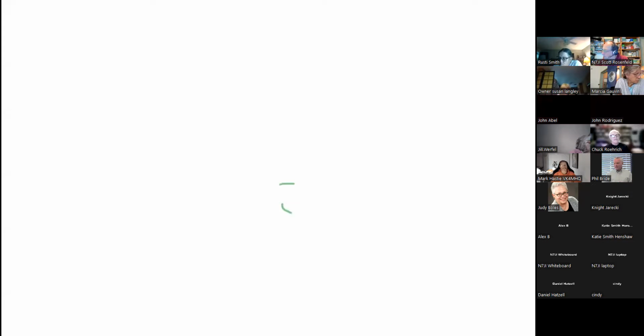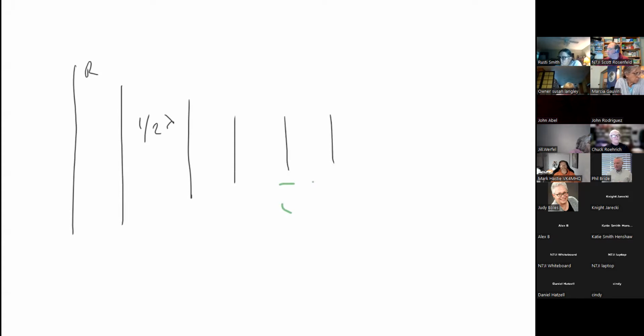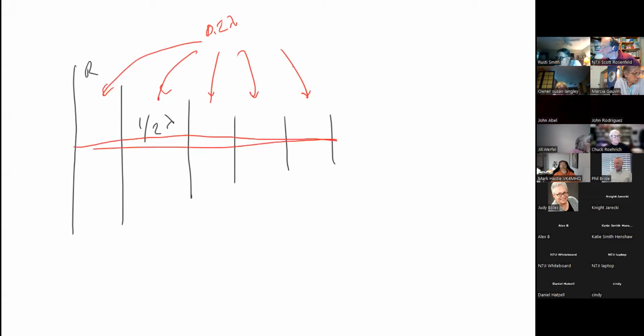At the core of the antenna, you're going to have a dipole, which is a half-wave antenna, so your driven element is a half-wave. Then you have a reflector, which is a little longer, and then a director, and another director. You can have as many directors as you want. Every additional one adds gain to the antenna. The spacing between elements is nominally about 0.2 wavelengths. So the length of the antenna, called the boom, is defined by how many elements you put on it and by the frequency you're using.